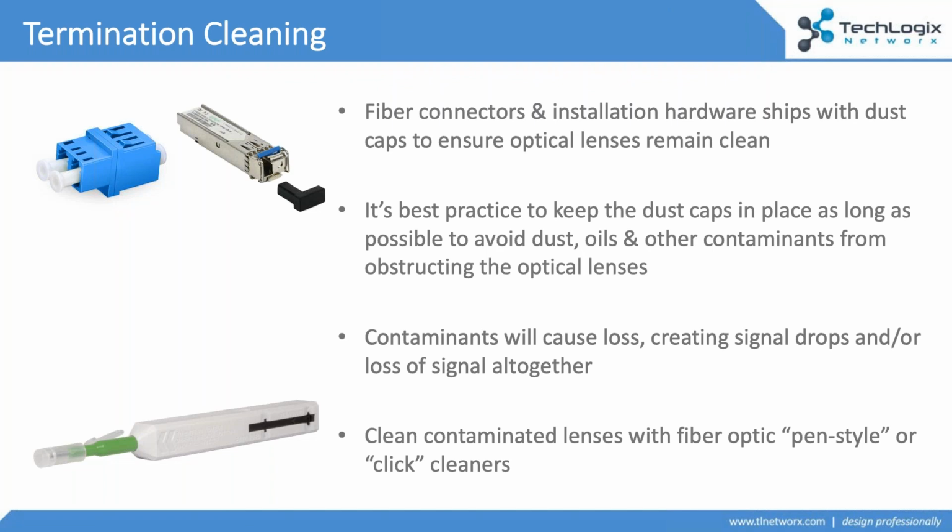As soon as you take that dust cap off, you can get dust in there. You can get oils from your skin in there. You can get all kinds of contaminants on those optical lenses. And because we're dealing with wavelengths, light, we're dealing with lasers, you just don't want anything disrupting the flow of information across that optical lens. So best practice is to keep the dust caps on as long as possible.